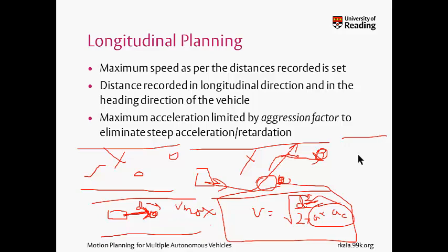The only problem that this methodology has is that sometimes the vehicle is in scenarios like this. It's basically oriented in this direction, so I not only measure this distance in the forward direction, I also measure distances in the heading direction of the vehicle, and the minimum of the two is taken. This is a distance which was not being measured previously, so it's a new distance I'll have to measure. And accordingly, at every time, I'll set the maximum possible speed such that it does not collide. Now remember, the problem with a high speed was only that it was colliding, it was bumping. If I can stop that, I can make the vehicle nicely navigate this, and that's what I have done.